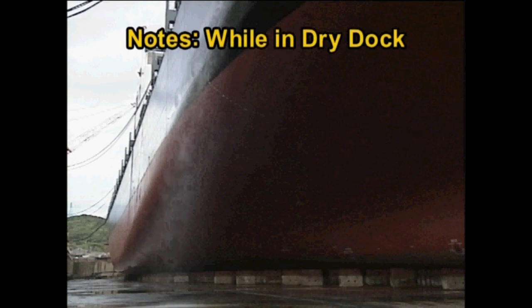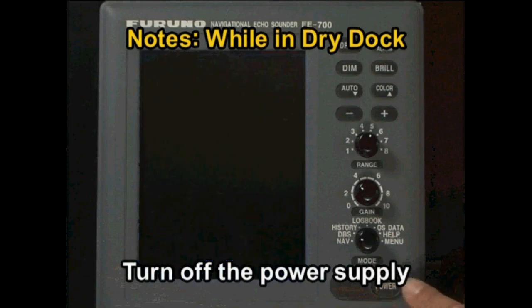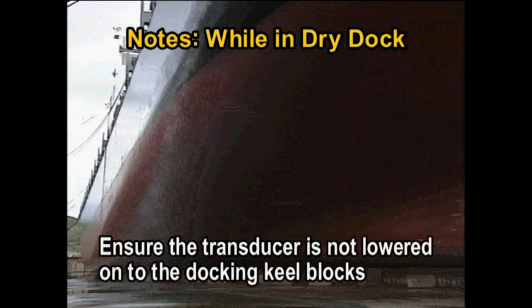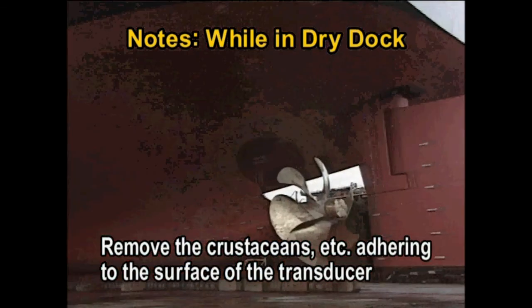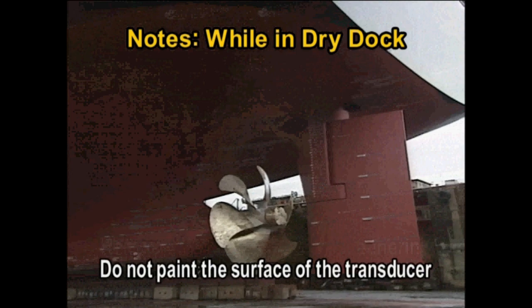Precautions to take when the ship is in dry dock are as follows. Turn off the echo sounder's power supply. Ensure that the transducer is not lowered onto the docking keel blocks. Remove crustaceans, etc., adhering to the surface of the transducer. Do not paint the surface of the transducer.